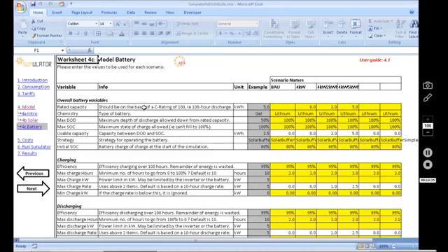So the first row is the rated capacity of the battery. In a business as usual situation, we've got no battery, it's just blank. And in the 4 kilowatt scenario, that's meant to model just solar panels on the roof but no battery, so zero or blank has the same effect in Sunulator. Now our 4 kilowatt of solar 2 kilowatt hour batteries, not surprisingly, has 2 kilowatt hours of battery storage, and the 5 kilowatt hour has 5 kilowatt hours of battery storage.